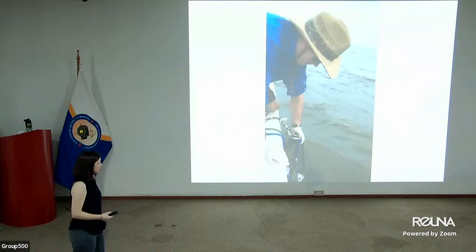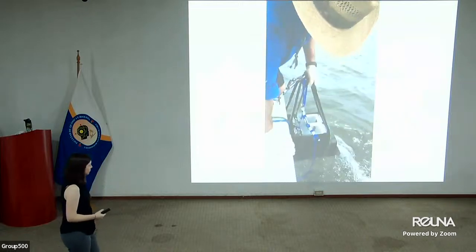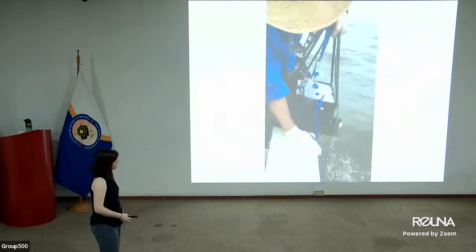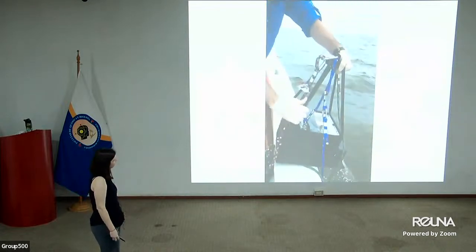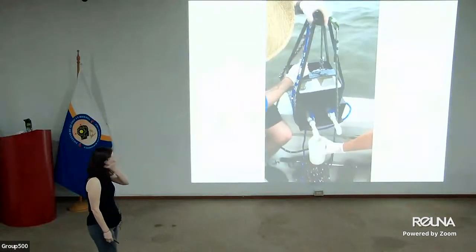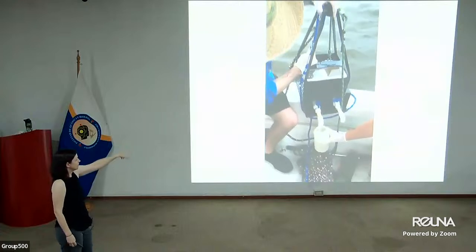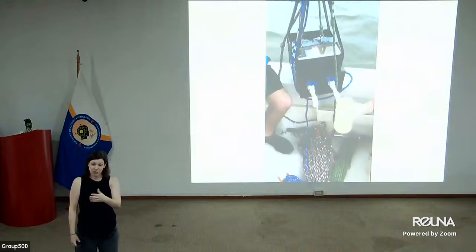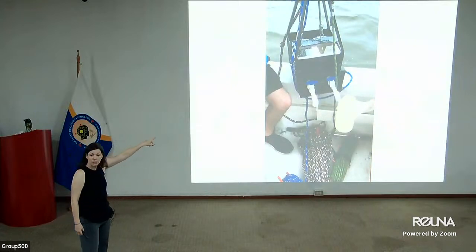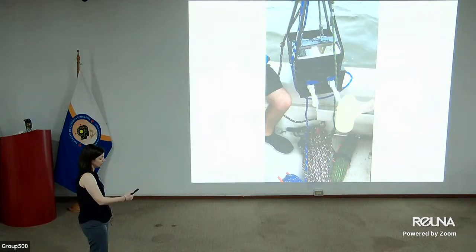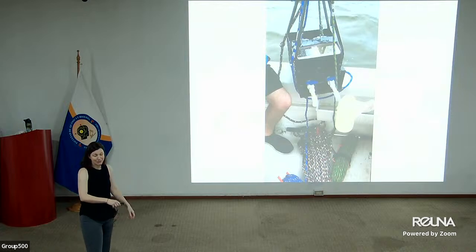And we tested this thing like crazy before we used it. Here it's just draining off extra water that it took. And then it's got these spigots, and then we collect our sample. This sampler would be entirely turned over and cleaned between sites. And so for our negative control, we would pour water in here and run it through to make sure there wasn't any DNA residually in here. And we even tested our cleaning method to make sure it was solid.